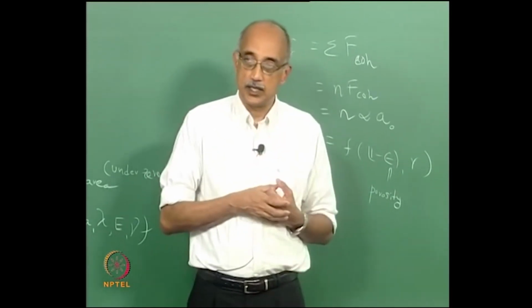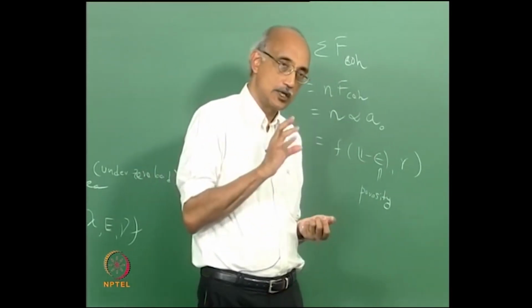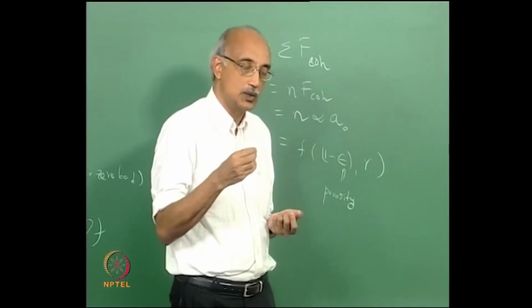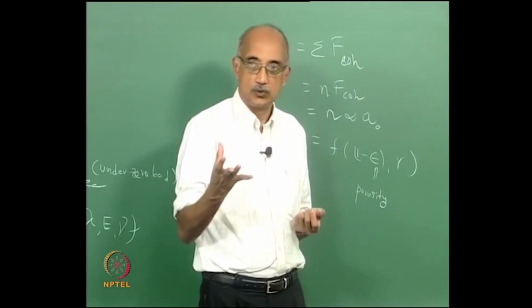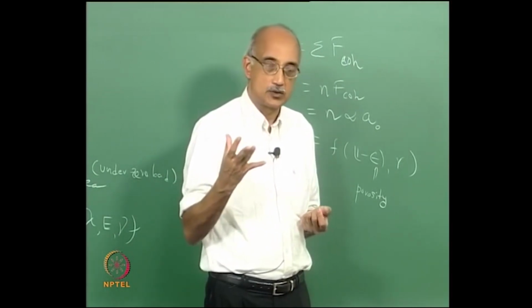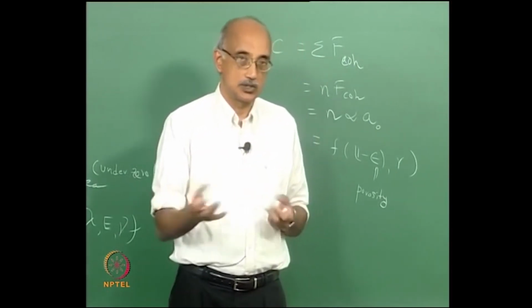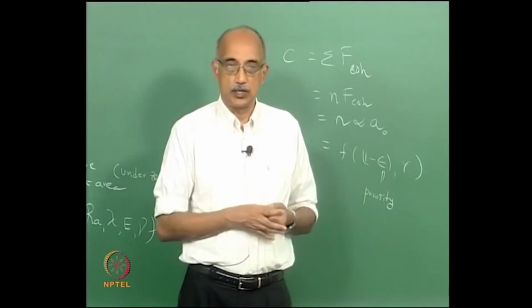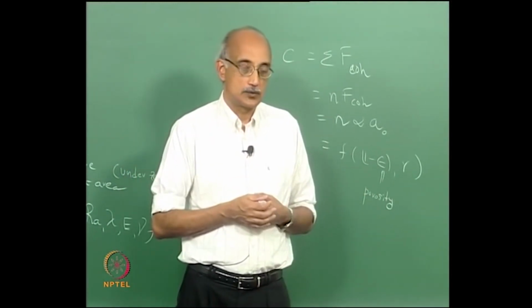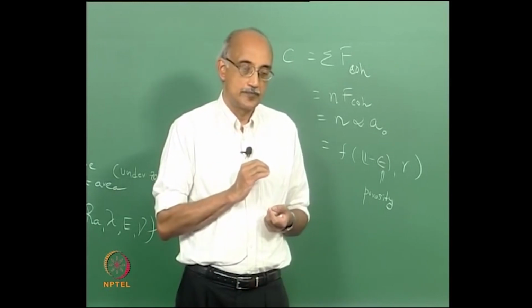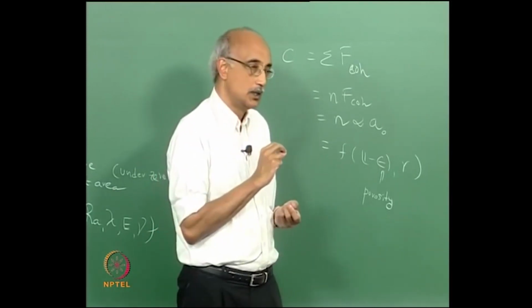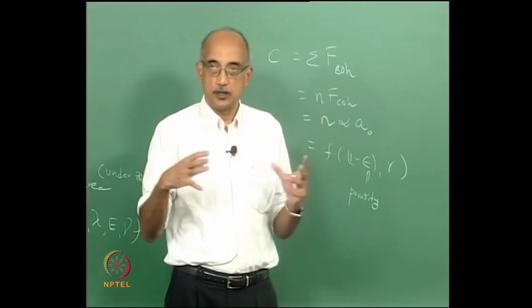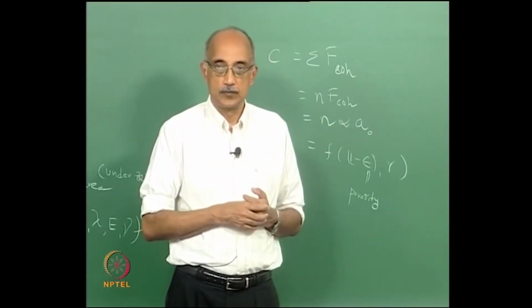Fertilizer industry, again the formulation is very important. You typically want to supply, for example, pellets to a farmer. The pellets, as soon as they are introduced into the soil, quickly break up into their fragments. So pelletization is another area where interparticle cohesiveness plays a huge role in dictating the integrity of the pellet as a whole.